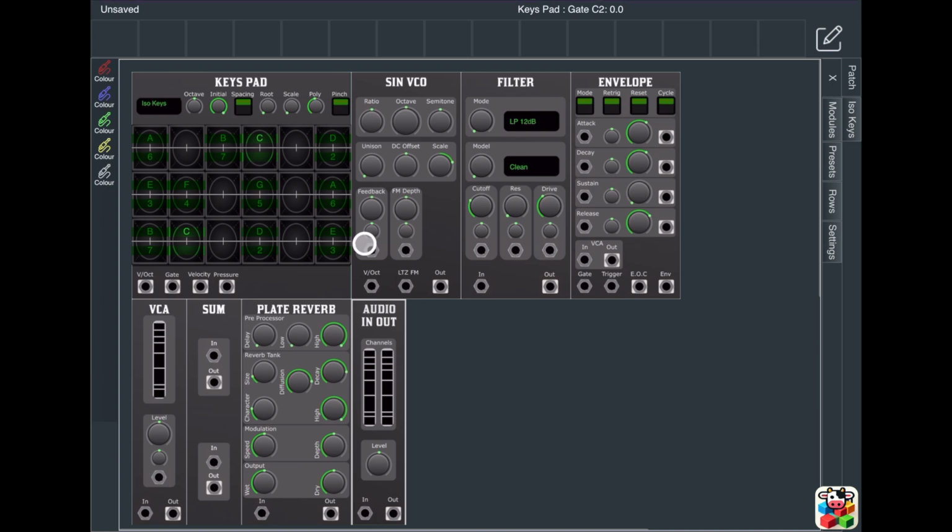To place a cable, select the color from the toolbar. Then long press on the port and drag to an input. While you place the cable, the ports will enlarge to indicate you can connect the cable. If you wish to move the cable, you can drag the end of the cable to a new port. To remove the cable, start the drag and drop and simply drag over a non-port area.